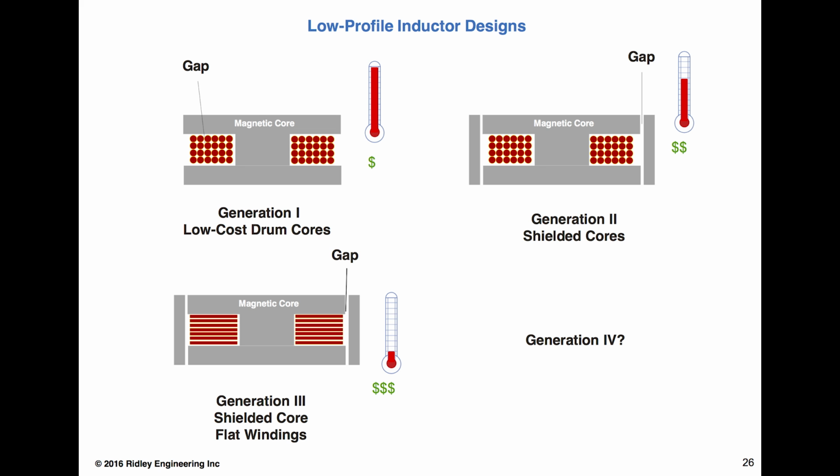So yes, there are some applications where we're still hard switching, but if you look at, for example, the server industry, they're the most advanced efficiency supplies that you can buy, running 98% including the PFC, which is just amazing. If you'd done that in the 1980s, you would have made a fortune. But how do they do it? Well, they're using FETs.